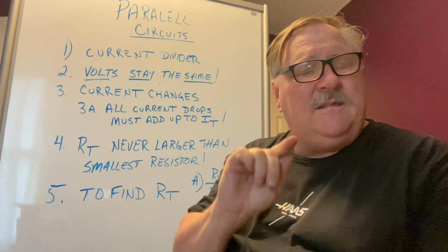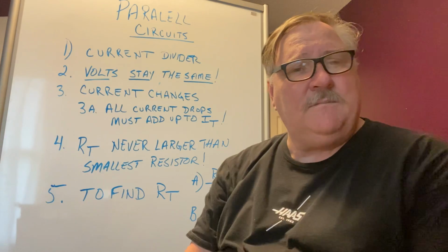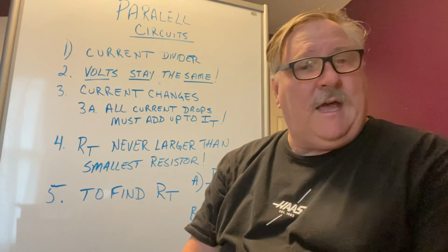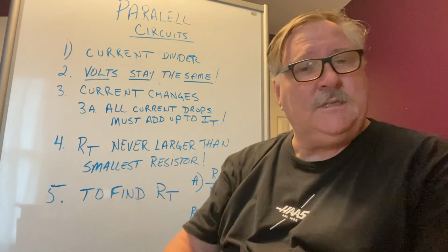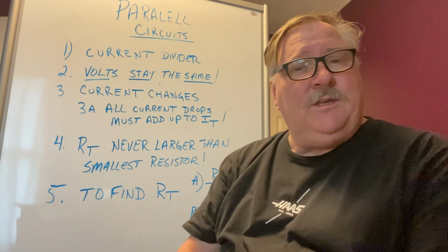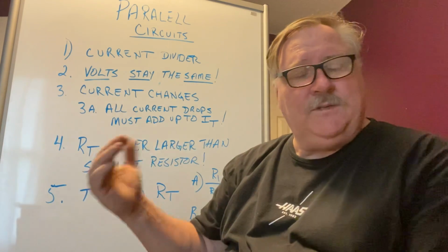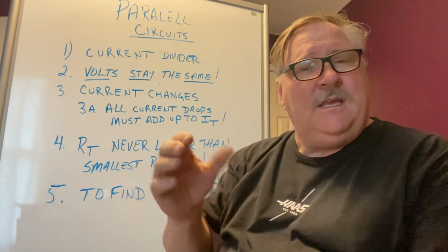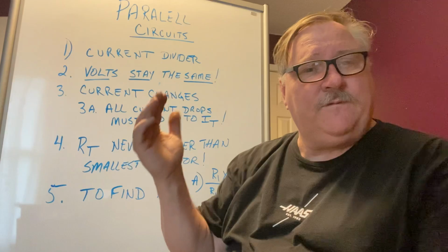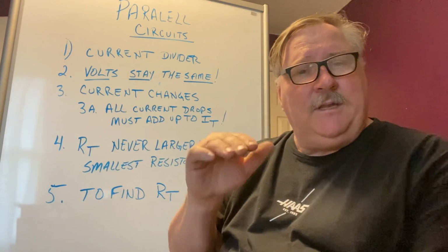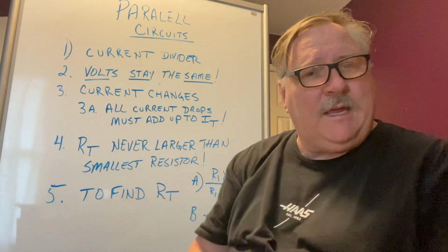But the current that is allowed in the bedrooms is typically maxed out at 15 amps. On the other hand, for the currents allowed in the kitchens, you have to have at least two separate 20 amp counter circuits. It's National Electric Code required. So it's dividing the 200 amp service, which is a typical residential service. You have 200 amps coming in, and it's divided. You have 120 volts going throughout the house. You have 240 volts total coming in off that transformer, off your pole or off the pad mount, coming into your panel. And then it's all parallel circuits after that, okay?